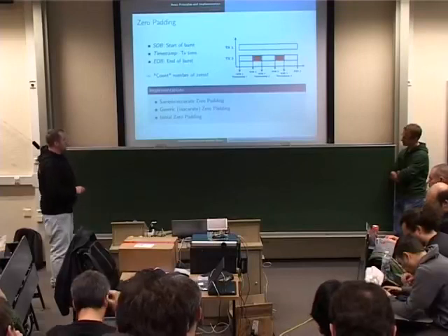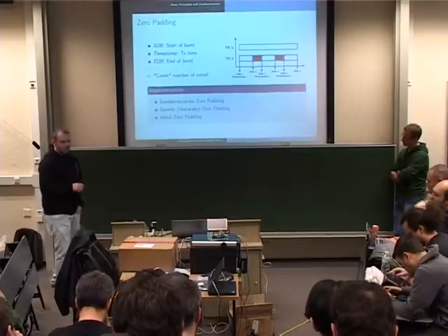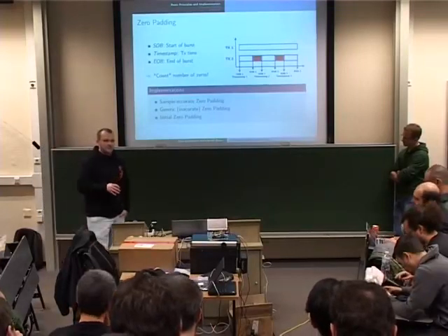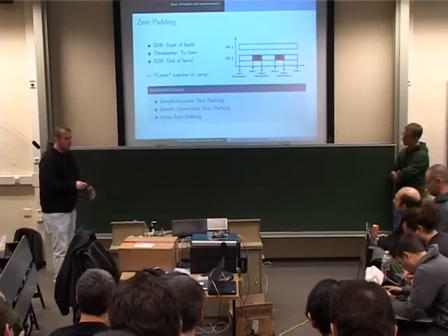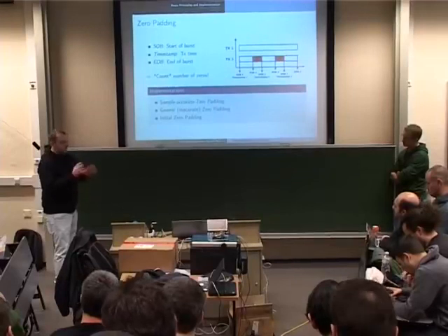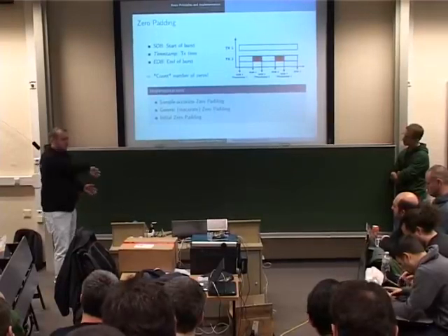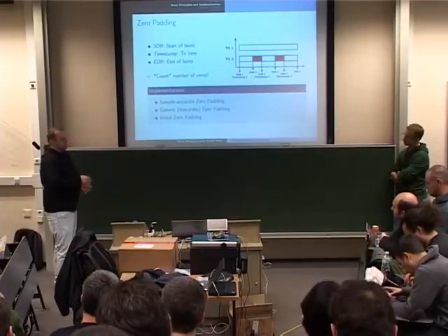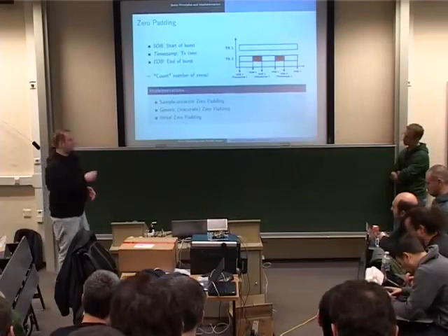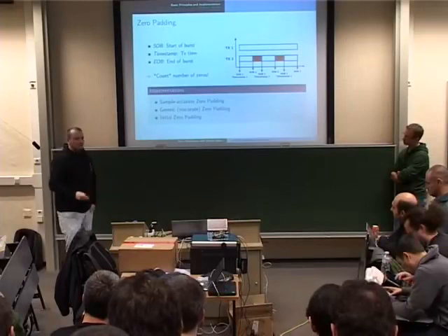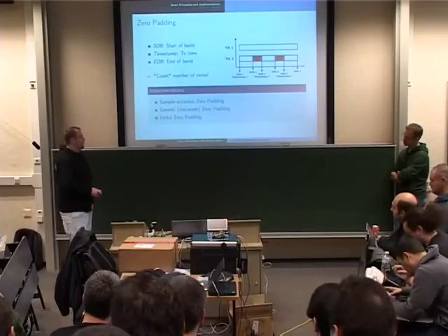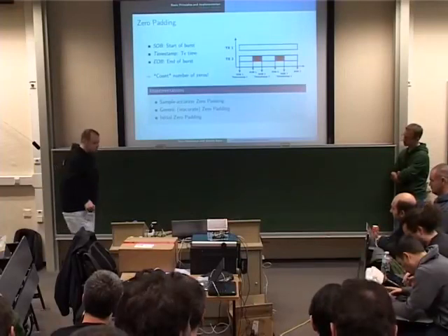And there's also the initial zero padding, which is important if you have transceiver systems whose output depends on the input. So there's a chicken and egg problem at the beginning. When there's no input, the transceiver produces no output. Therefore we implemented an initial zero padding which produces noise at the start if the work function doesn't get an input.